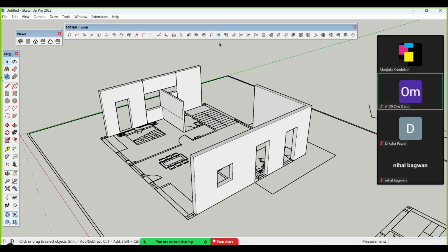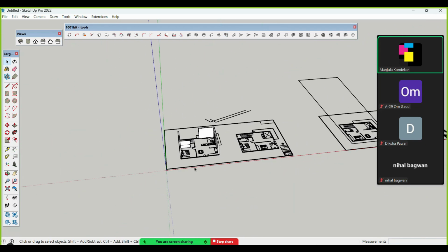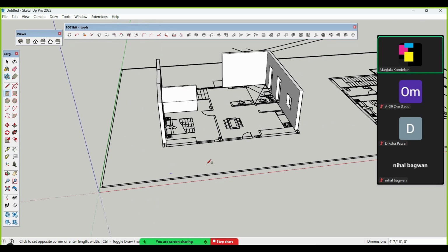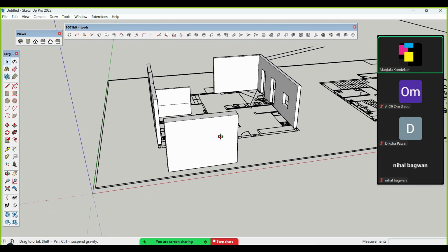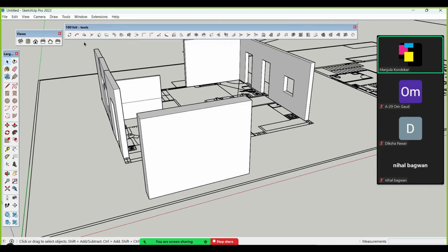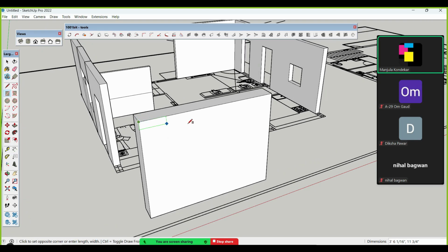Next we create horizontal groove lines. Actually, earlier we saw that. How to do the groove line? For example, if I have a front wall and I want to create grooves, there is one more option. The first option is you can divide the edges, draw the lines and do a push and pull. Or else I can directly take a rectangle.